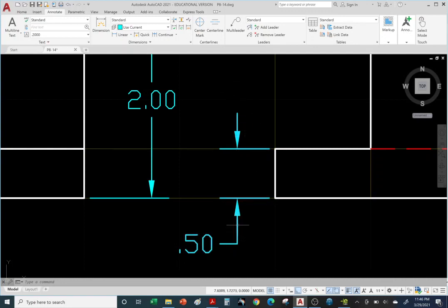Another option is to place the arrowheads inside. That's another option. I can flip the arrows. As long as it doesn't look crowded, that's acceptable also. So either of the three is acceptable: arrows inside, or text inside, or all three outside. Either one looks presentable.